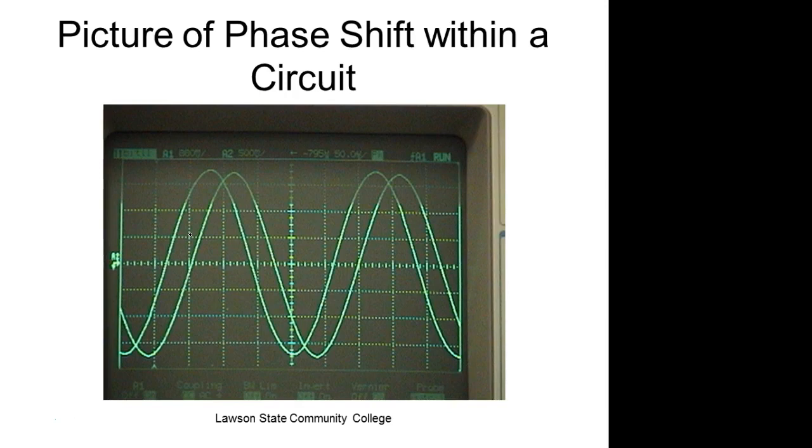What is the power factor? The motors actually have a rating, and we'll get to that. So we have a plate on the motor called a nameplate. All your motors now have to specify a capacitor that you put in the circuit to take out the phase shift of the motor, to increase the efficiency of the motor. These old motors didn't have that. So all your new motors have a little thing on the faceplate where you can figure out what size capacitor to put in parallel with it.